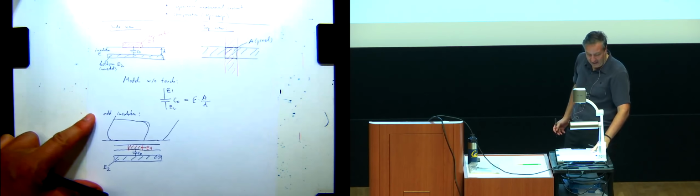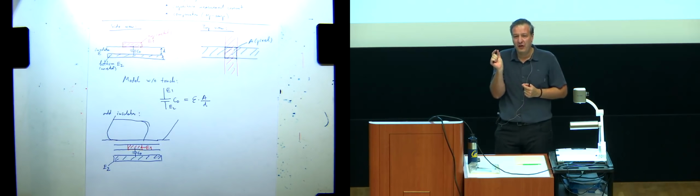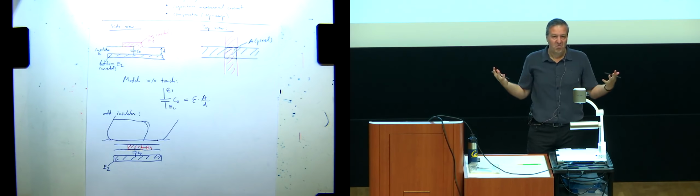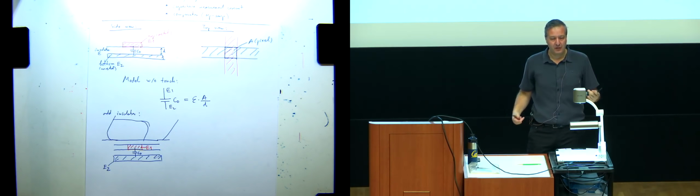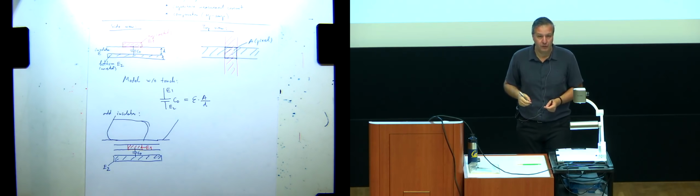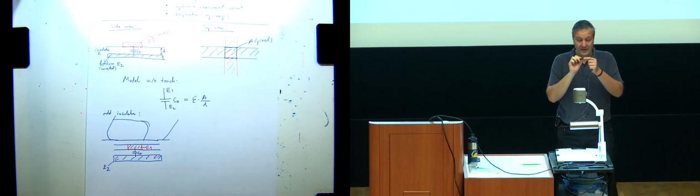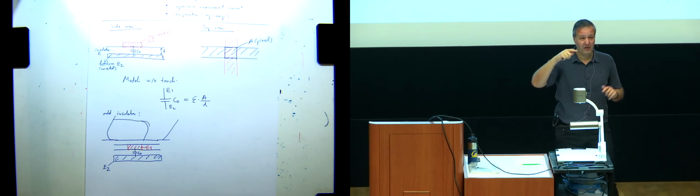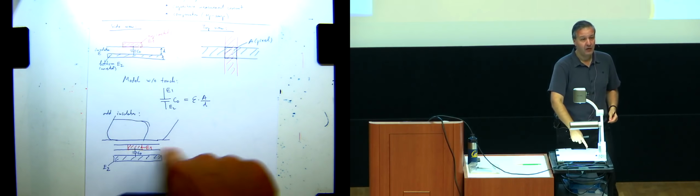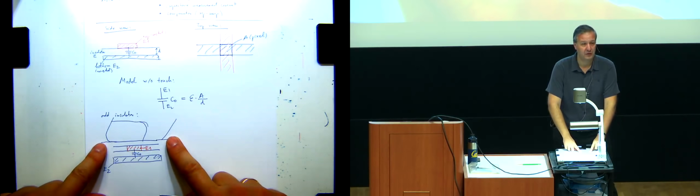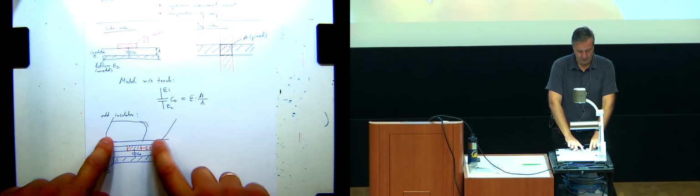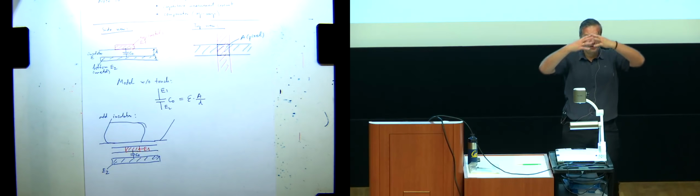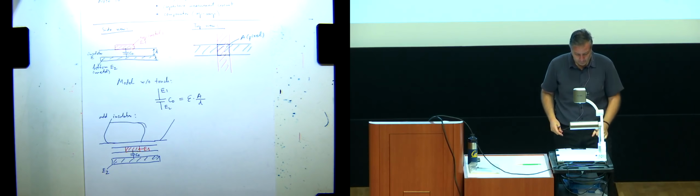Right? And actually I've shrunk the finger. In reality, you have a couple thousand by a couple thousand pixels on your phone. On larger screens, even more. So when you touch with the pen that you're writing on your tablet or on the phone, the tip of the pen already is covering several pixels. Not to mention when you press with your finger, there are many, many pixels that actually see your finger. So I've shrunk the finger in this picture to be a lot smaller with respect to the pixel than it really is. So really the finger acts as this giant plate on top.